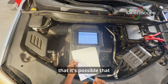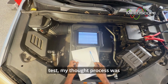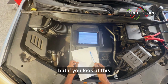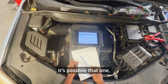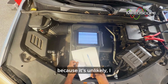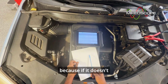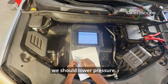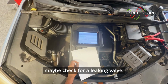What this tells me is that before we did this test, my thought process was maybe the pump is not putting out enough, but if you look at this with the max delta of 1.25, I don't think both valves, because it's unlikely. I think one of the valves may not be closing well. That's a possibility. If it doesn't close well, in the open state, it will show just fine, but in the closed state, it will show lower pressure. So what I want to do next is to check for a leaking valve.